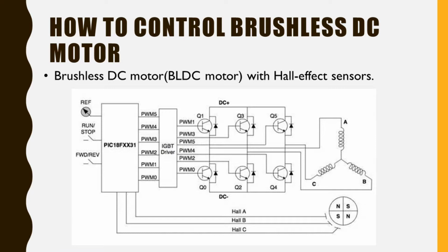This system shows the three coils of the motor arranged in a Y formation, a microcontroller, an insulated gate bipolar transistor, IGBT, driver, and a three-phase inverter comprising 6 insulated gate bipolar transistors. The output from the microcontroller, mirrored by the IGBT driver, comprises pulse width modulated signals that determine the average voltage and average current to the coil, and hence motor speed and torque.